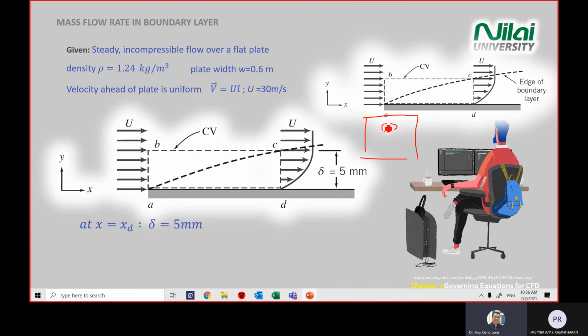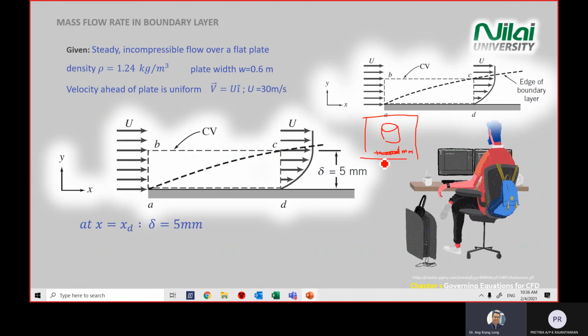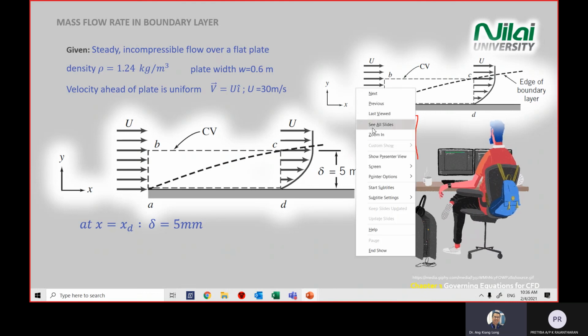Let's say you have an object inside the project window here. There's a ruler bar below here in ANSYS, so you will see whether it's meter or mm below here. There's a black color, white color ruler here. Okay, so make sure you set the correct dimension when you run any simulation.